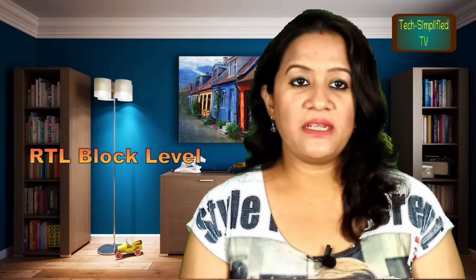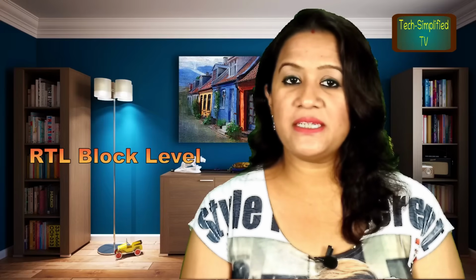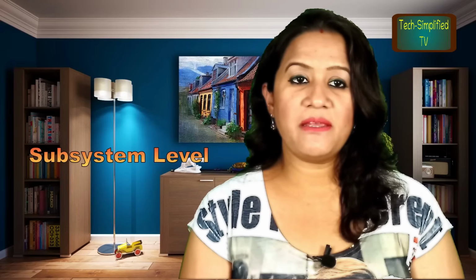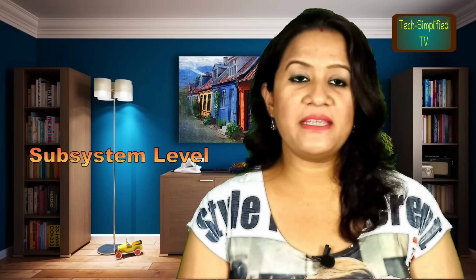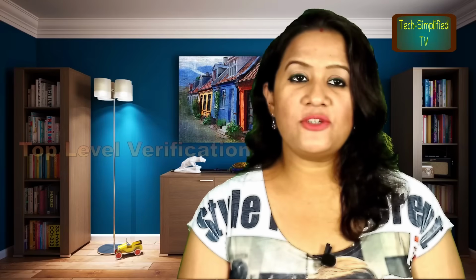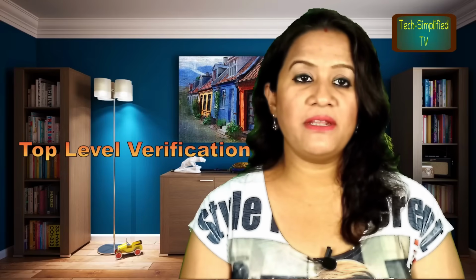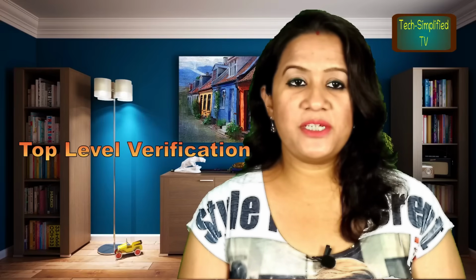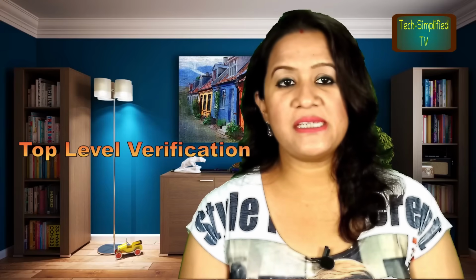First, unit blocks verification. The verification can be made at the RTL blocks level. Thus, we test all the functionalities of an IP through simulations. Second, verification at the subsystem level. The verification can also be realized at the subsystem level, including several IPs. Then we check all their functionalities and their integration in the subsystem. Third is top level verification. Once the RTL design is verified at the unit level, we can integrate it at the top level.